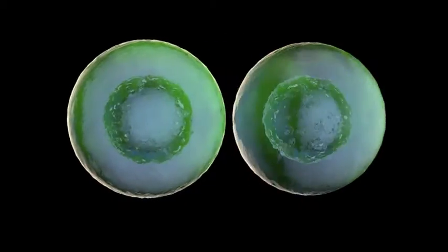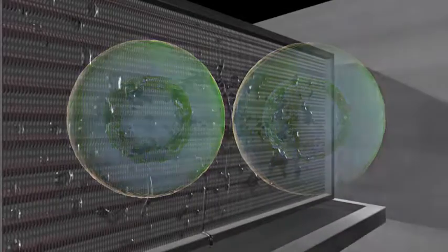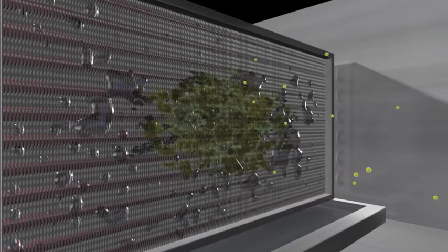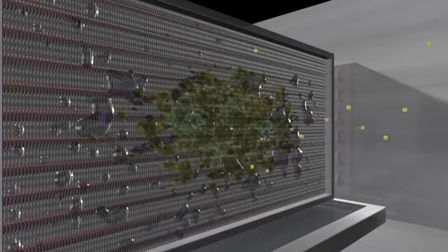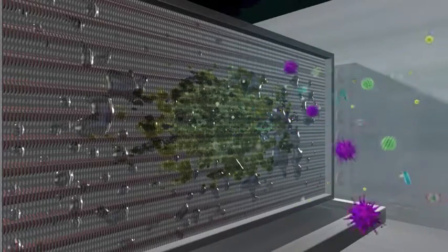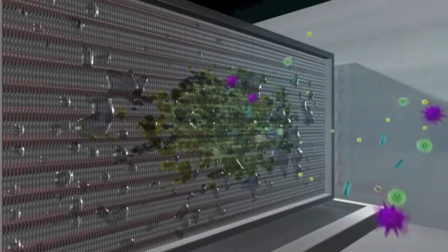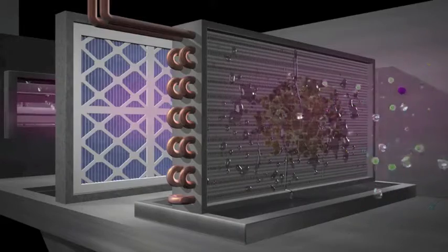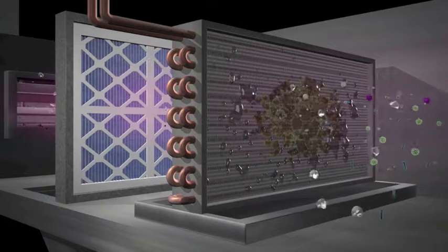Mold takes 4 to 6 hours to double, so it can easily multiply into 1 billion organisms in 12 days. As long as it's alive, it will cling to the coil fin. Its sticky surface attracts and grips the dirt, forming the biofilm. The biofilm reduces the heat transfer function of the coil, and consequently the air is not cooled sufficiently, nor is the humidity removed.